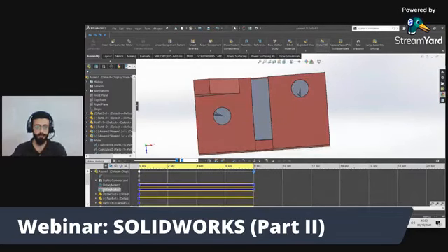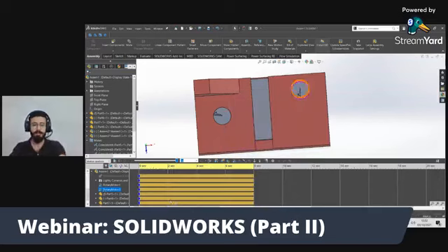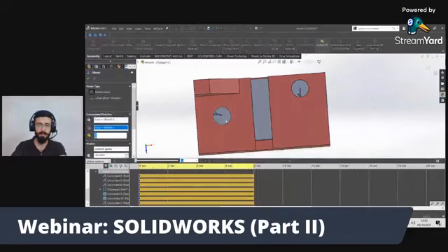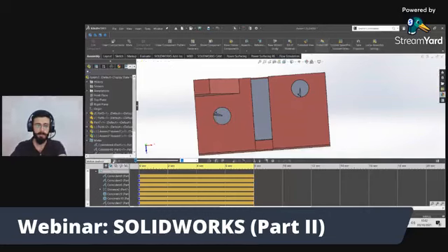There is an issue on motor 2, because let's remember one thing. I have paused my assembly here. Let's suppose it's 5 seconds. So whenever you are going to edit your assembly, just slide the time bar to 0 seconds, then add your motor. I will be adding it here. Make it clockwise. RPM should be 25. And now calculate the assembly. See, everything is good and fair.